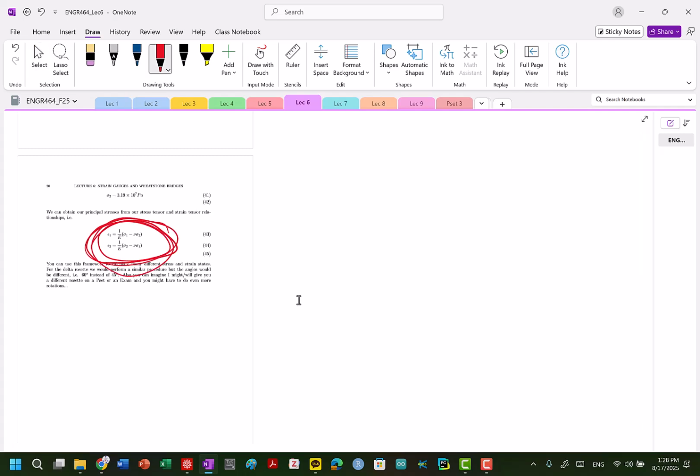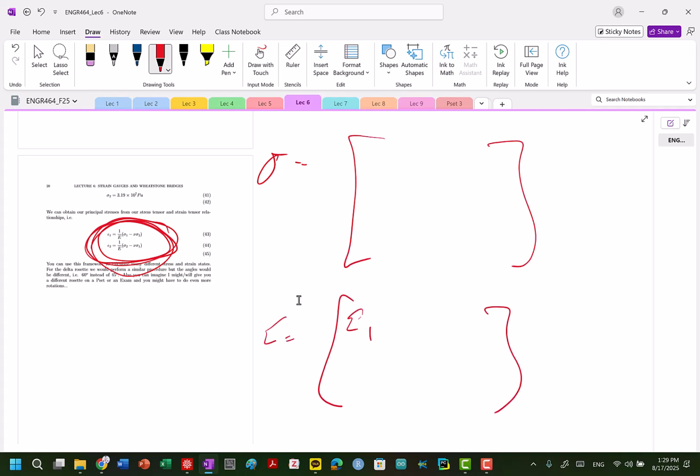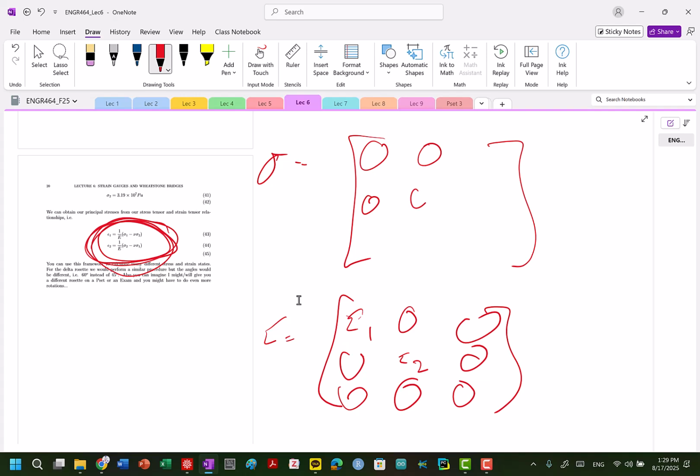This is not the most common notation. You do have to understand, once you're in the principal strain state. So for example, once I've defined that I'm lying on this circle, and really I'm in a state like this because we're looking at plane stress. So once I've established that this exists, we know there's nothing here, there's nothing here. Is there a stress in the 3-3? If there's no strain in the 3-3, that's not necessarily the case, but we can basically calculate it from here and here.